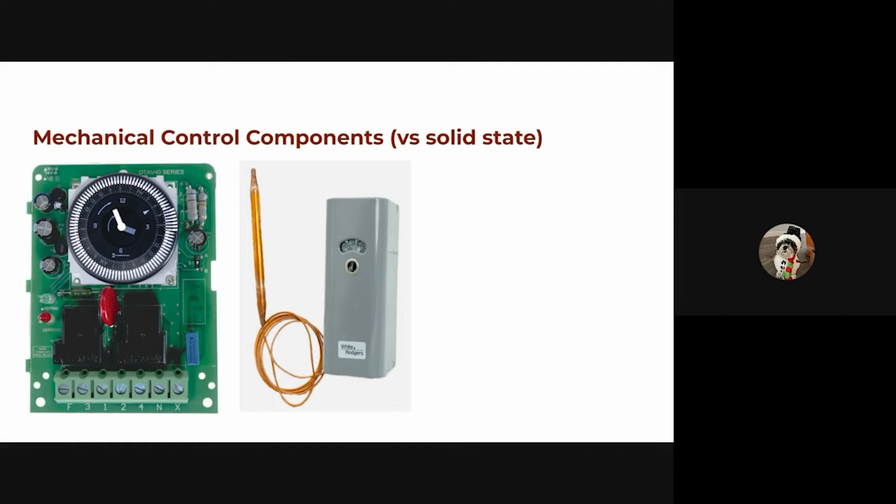And then in the case of a local compressor, we may have two of these. There may be one for early termination of defrost and one for control of the compressor itself, just to maintain the refrigerant at the right set points.